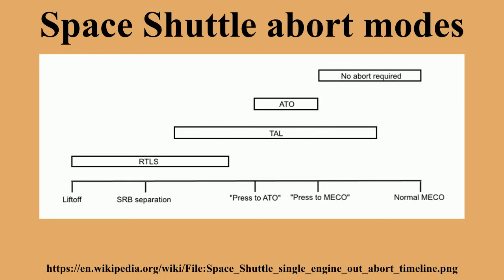Before the Challenger disaster, this almost happened on STS-51F when a single SSME failed at about T+345 seconds. The orbiter in that case was also Challenger. A second SSME almost failed due to a spurious temperature reading, however the engine shutdown was inhibited by a quick-thinking flight controller. If the second SSME had failed within about 69 seconds of the first, there would have been insufficient energy to cross the Atlantic. Without bailout capability, the entire crew would have been killed. After the loss of Challenger, those types of failures were made survivable.